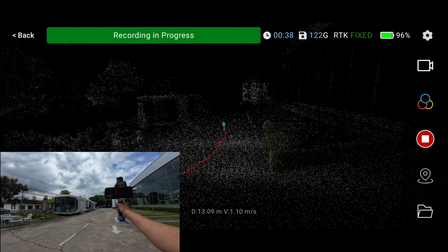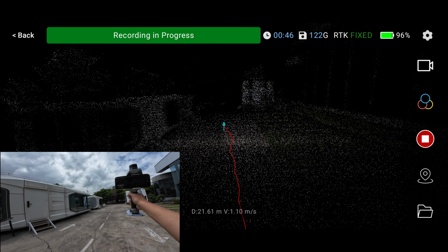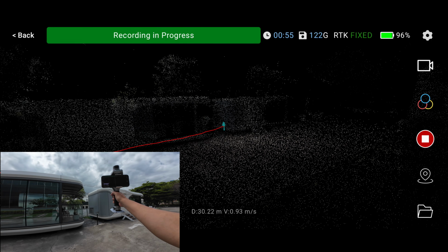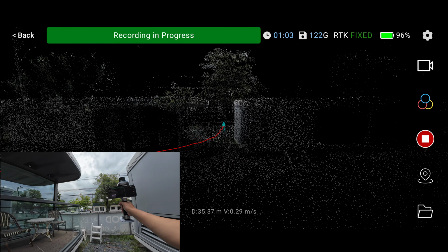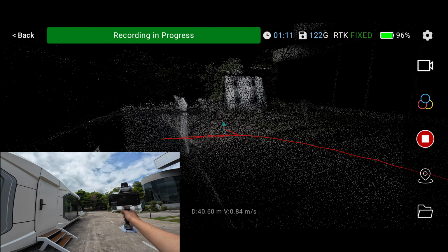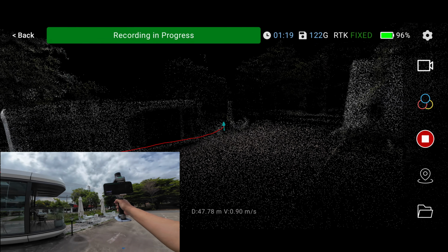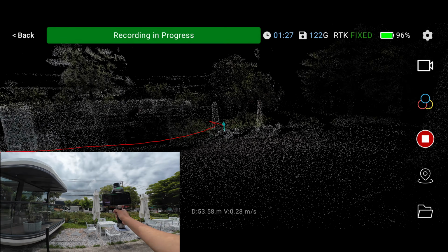These capsule houses have walls that sit flush with the roof, so there is no real protection from sunlight. In Thailand summer, solar load can reach around 400 watts per square meter. Even though the walls are insulated, the large windows let in a lot of heat, and curtains alone aren't enough to block that level of solar gain.